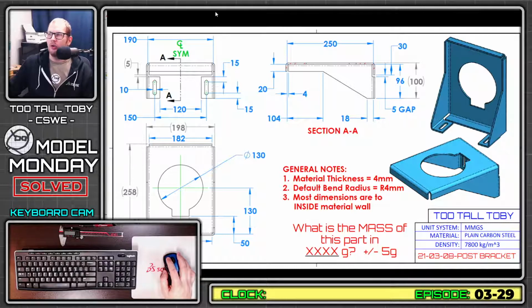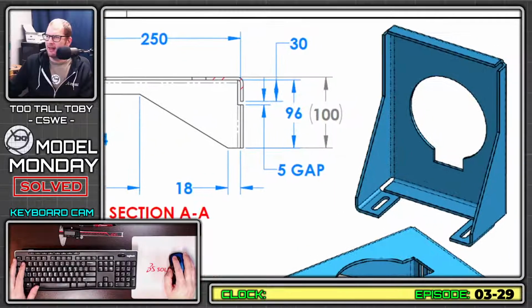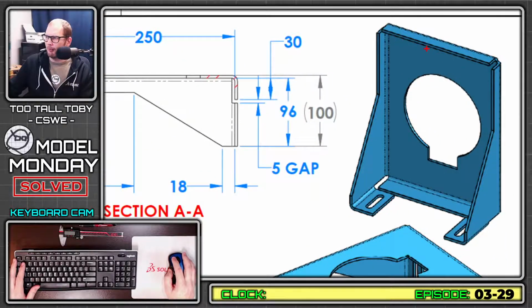All right, so as always, we start out with a game plan. When it comes to sheet metal, if I can capture multiple bends, so like if I'm going down the center line here, if I can get this bend and this bend and this bend all in one shot for the sheet metal design, it tends to work out just a little bit more intuitively. This was a conversation that actually came up on Saturday. If you model the whole thing in just like a rectangle and then extrude it out, you don't actually get a parameter for bend radius in that user interface, so it becomes a little counterintuitive.